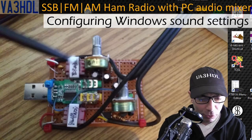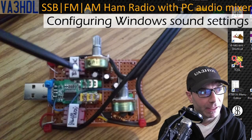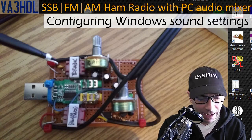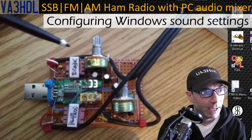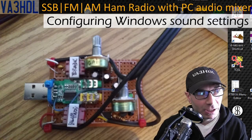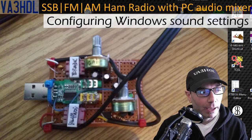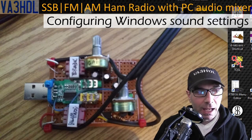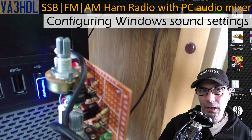You can see there are three cables going into the radio. One is for your microphone, the other is for your speaker, and the third one, in this case, I have for the push to talk, because I have a couple of transistors that do the push to talk for me. But this is entirely optional. You could do this without the push to talk transistors. So now I'm going to plug this interface into the computer and show how to configure it to use later for our project. Now we have the interface plugged into the computer.